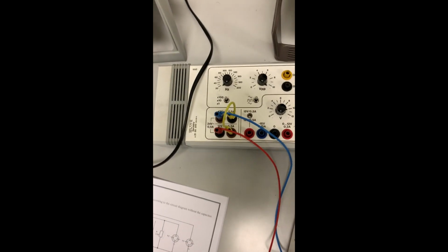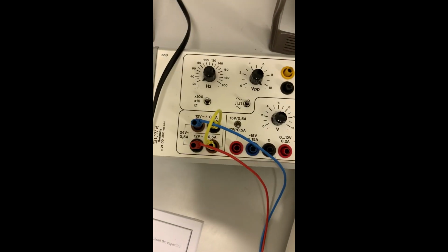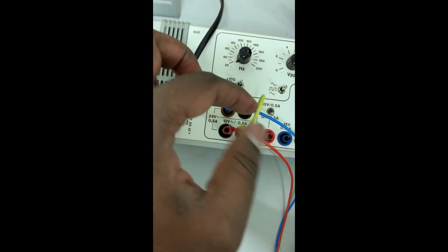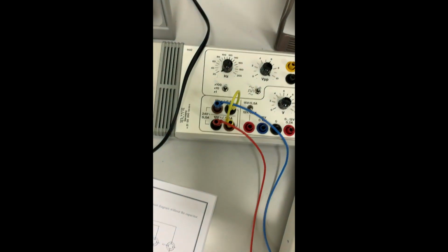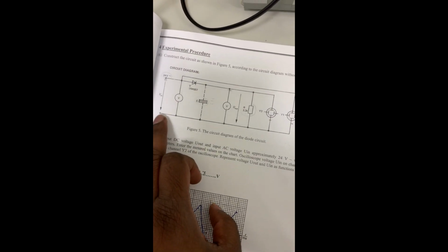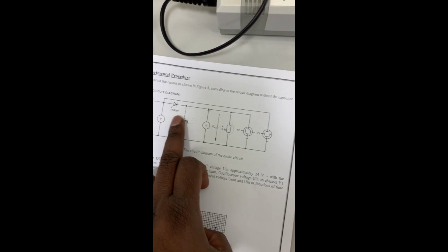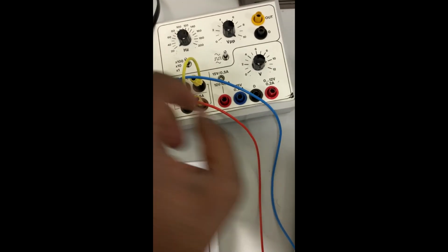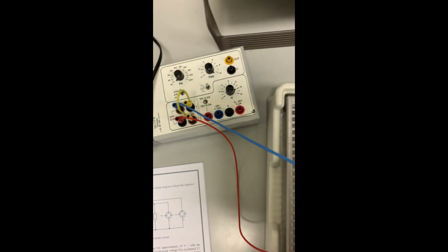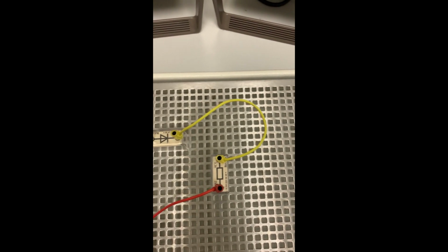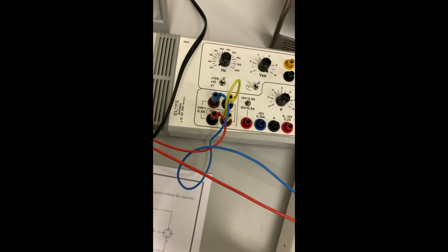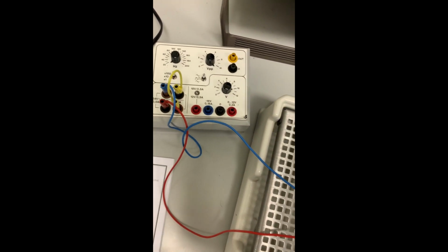This is the circuit diagram. This is the voltage power supply. Here we have 12 volts. We just put them in series to get 24 volts. And from this, according to the circuit diagram, from the 24 volt we give a connection to the diode, and the diode is connected to a 3.3k ohm resistance, and it is grounded, the red part. Now first we give the connection without any capacitor and check the output on the CRO.